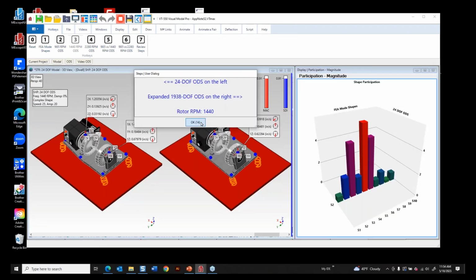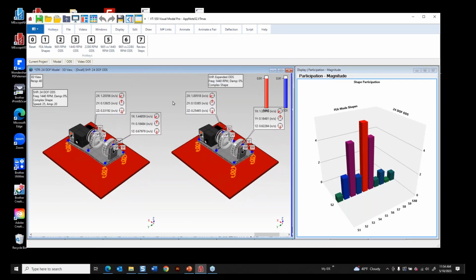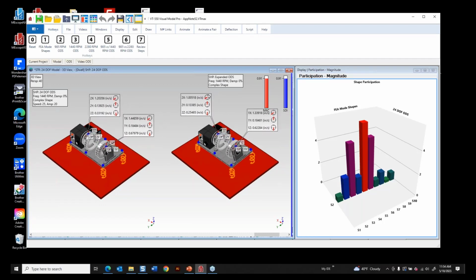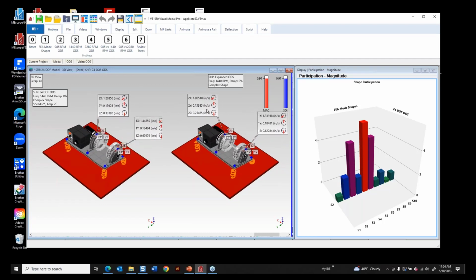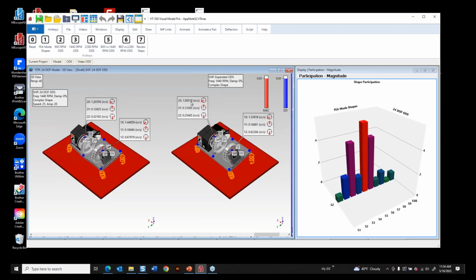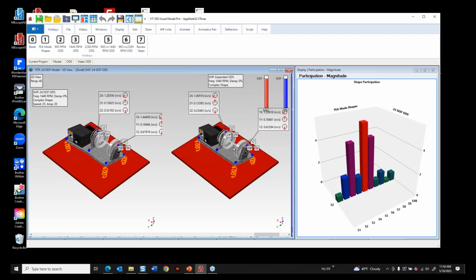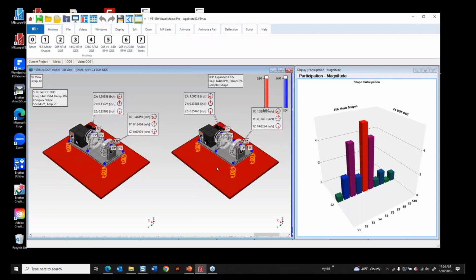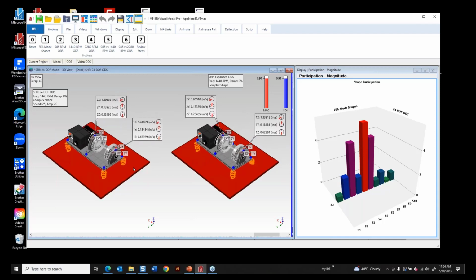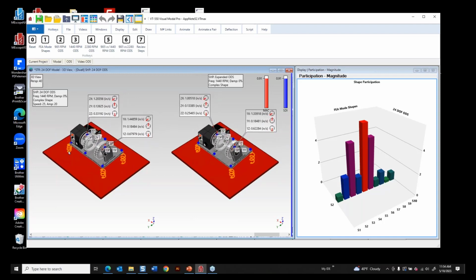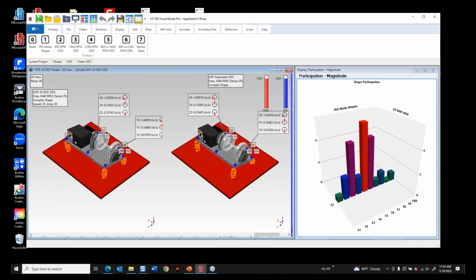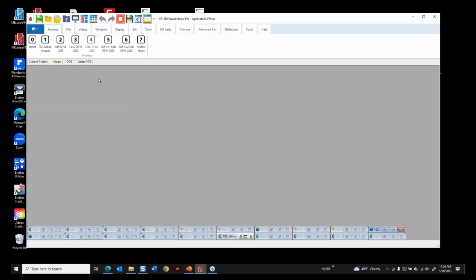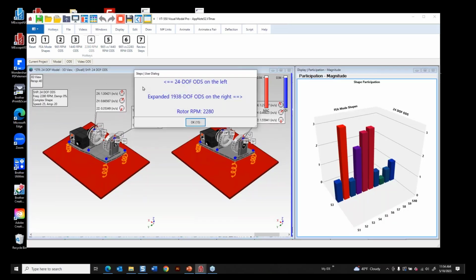Okay, so here we are with the 1440, and we've got some, again, look at those phases. They match up almost perfectly. And the motion is over an inch per second on the inboard rotor, quite a bit more motion on the outboard rotor, again in the transverse direction. So this is very realistic, to the degree that the accelerometers were calibrated properly. We're getting some very realistic motion of this machine in inches per second.